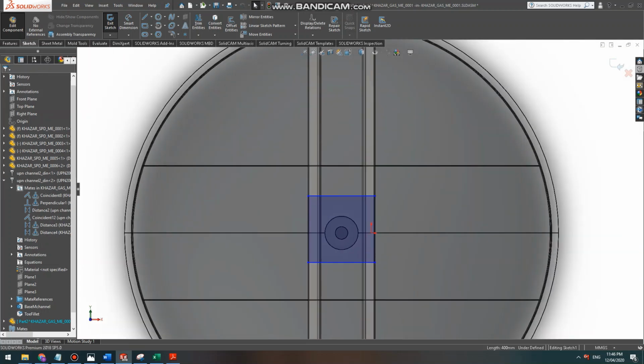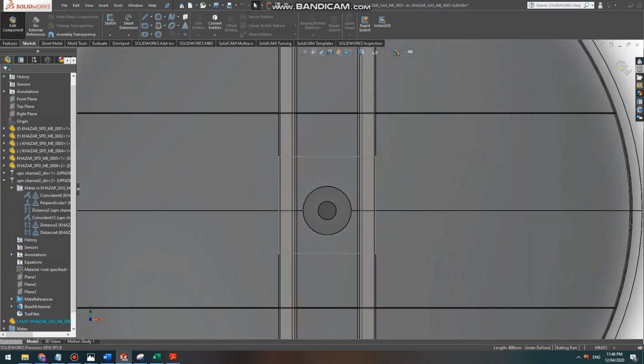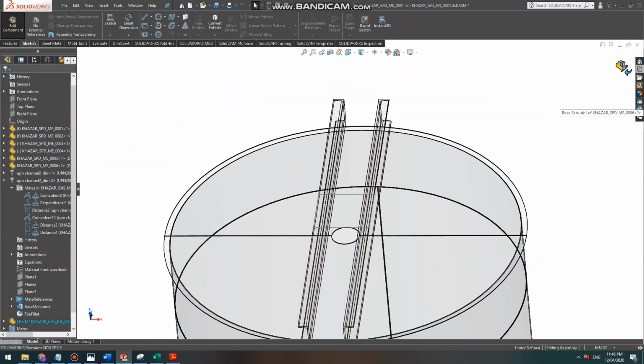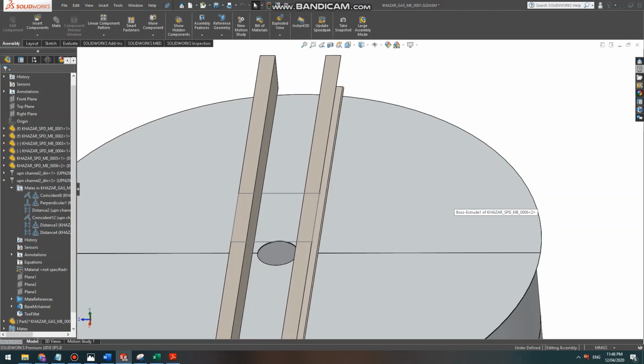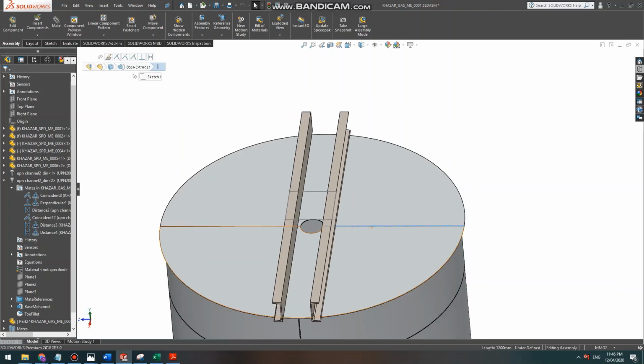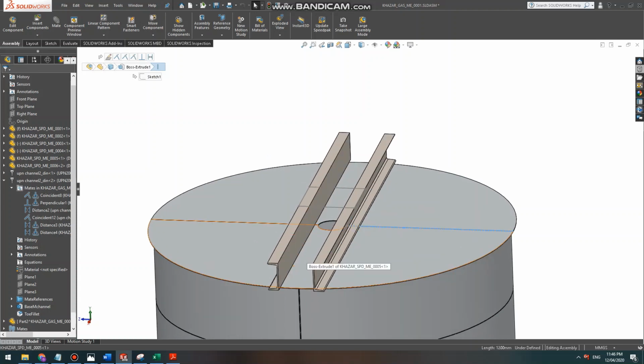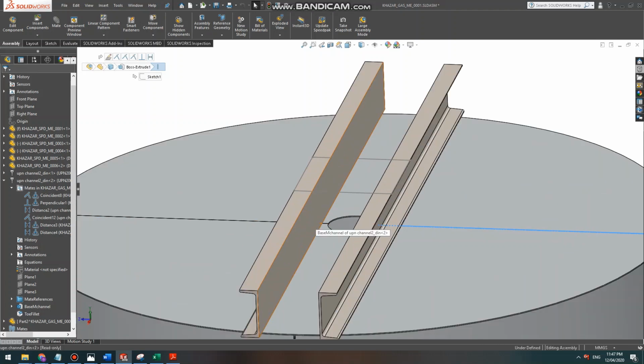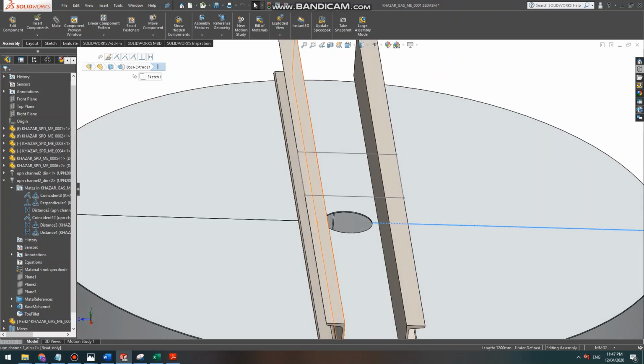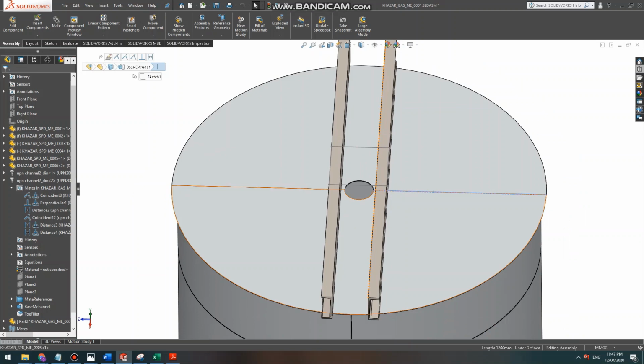And the point is, I have to tell you that if you see, there is a weld line here. We didn't put the ribs, these channels, parallel to it. We put them perpendicular to it, because when you put it like that, it gives more rigidity to the structure. If you put it parallel to the weld, it will not be that efficient a structure.